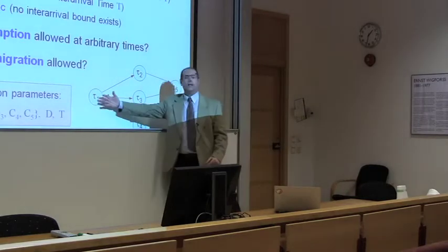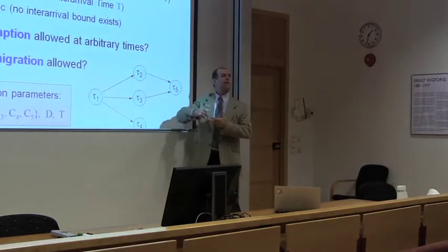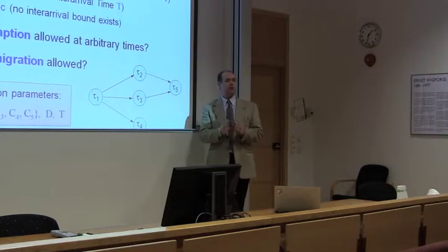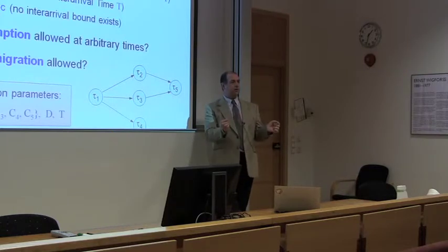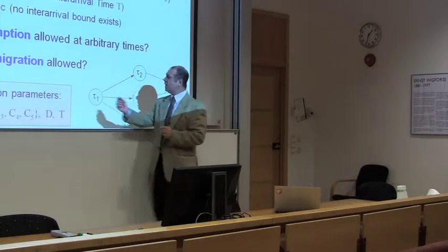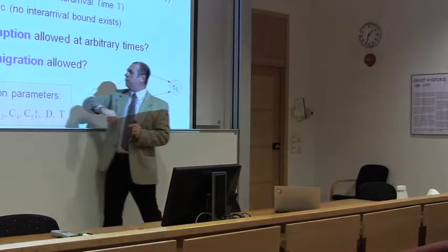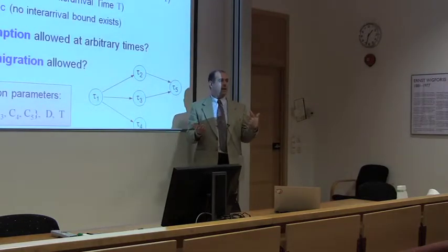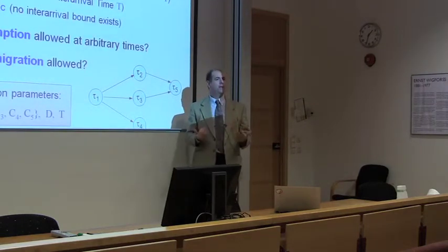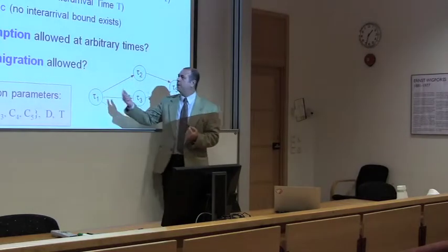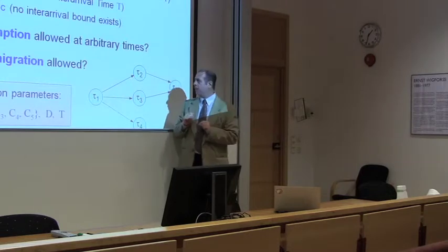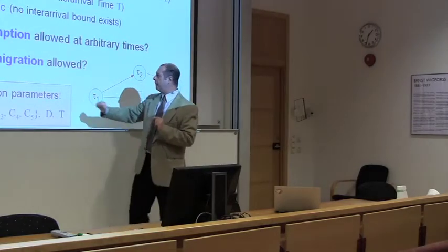So once you start executing a task, can you interrupt the task because another important application arrived or not? This is also another important decision to be made in order to perform the analysis. And of course, you may decide for a fully preemptive application or fully non-preemptive application, or something in between, partially preemptive application. So maybe the application can be interrupted only at specific points, called preemption points, for example.